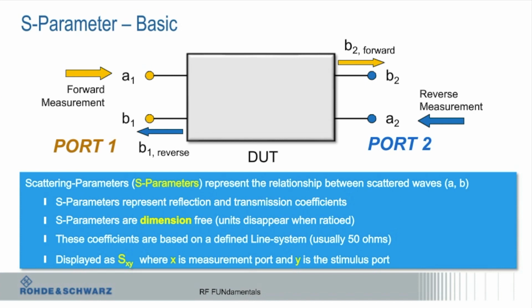So after you've done your cal, you measure something and see whether it looks like it did before, or like the model data that came with the kit. In the case of a verification kit, I have all the S parameters for each component. When I'm done with a cal, I'll pull up the S parameter file for that device, put it on the screen, and then put the measurement on top, and they should lay right on top of each other. That's really what you should do.